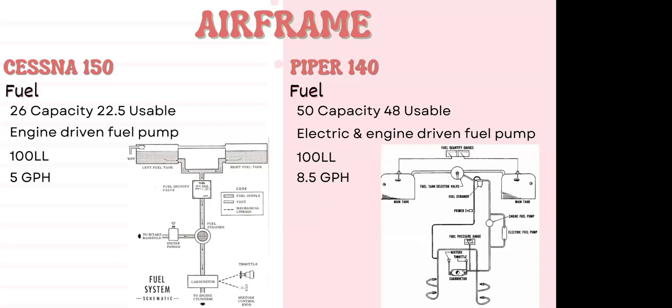And yeah, for the 172 Mike model, it's definitely gravity fed and engine driven. So just to clarify, even if you have a gravity-fed fuel system, you're never going to not have a fuel pump at all. There will always be a fuel pump in play, whether it's electric, engine, or both. Okay, that answers my question. Thank you. Oh yeah, you're very welcome.